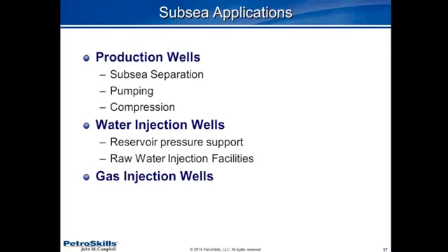They're also used for water injection wells, which may be used to dispose of produced water, or possibly for reservoir pressure support in order to enhance production, and also used for gas injection wells, which may be used to sequester gas, or possibly also used to maintain pressure in existing reservoirs.